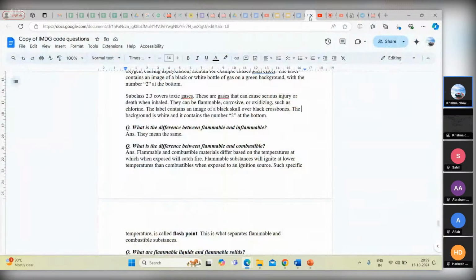Finally, the chief officer is checking in the loadicator, where all these requirements and information, whether separated from or away from, as per the cargo, are already fitted. He will just enter the stowage plan from the shore. If there are any alarms or something is missing, or he wants to change something manually as per the rotation, ETA, or different types of cargo, he can do that.